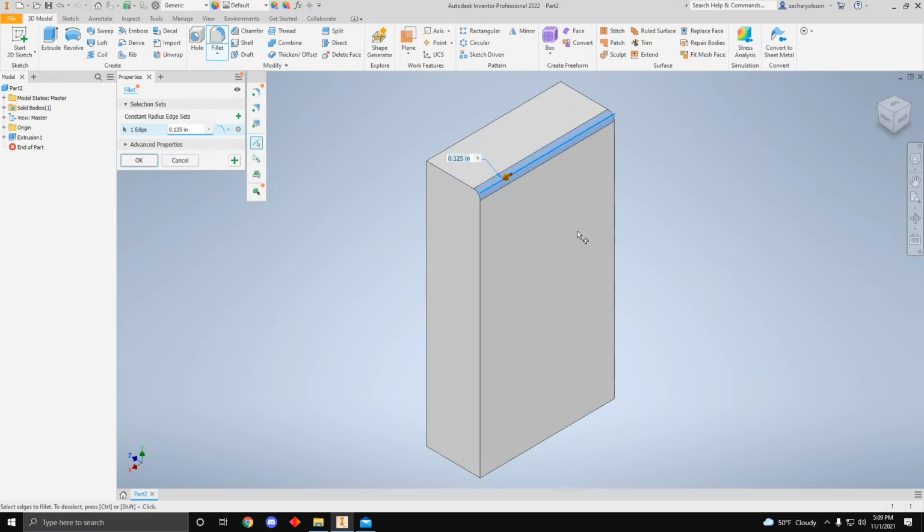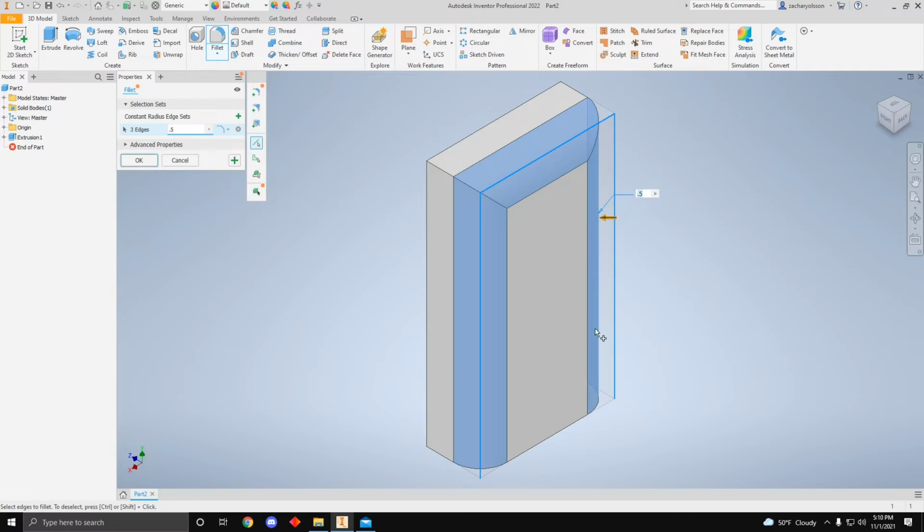Obviously, we want it to be a little bigger because the phone is more tapered, at least on the back side, like a landline, it's going to go back. So just for the back side, we're going to say 0.5. And that's going to do a decent amount of fillet there and make it round off. And then if we grab this edge, it'll do the same. And then this one. And we're going to do the bottom too. I was tempted to leave the bottom, but realistically, if it's on a charger, it's not going to be that wide at the bottom. So you do that, and then you just click OK.